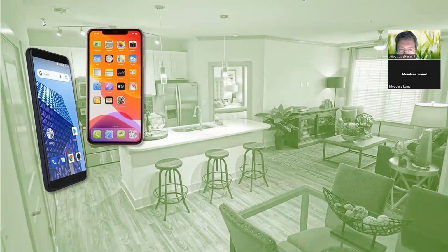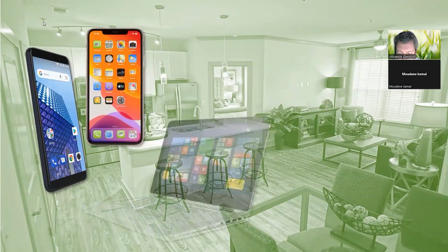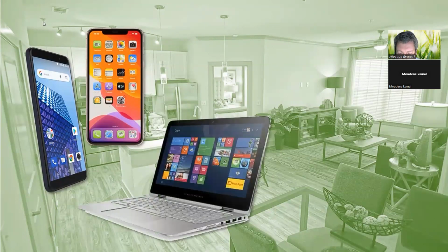Outside the mechanical and automotive industry, many objects of everyday life are also controlled for functional reasons or appearance. The metal shell of a smartphone must have a soft touch that ensures a good grip, but should not be marked with fingerprints. It should not get dirty too easily and must also offer a luxurious look. Its surface texture is controlled by many complex specifications. The front glass protects the screen, but it is also a tactile area which must accurately respond to the fingers of the user. Grained plastic of a laptop case or of the keyboard keys provides comfort of touch and effectiveness in operation. Connectors must ensure good electrical contact and sufficient clamping during insertion and withdrawal.